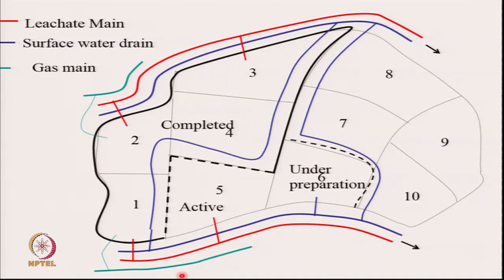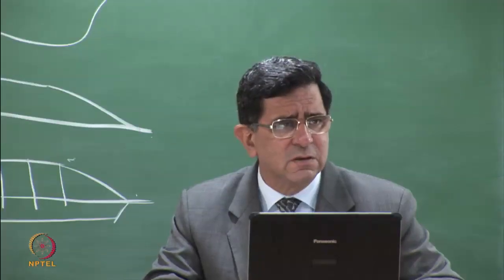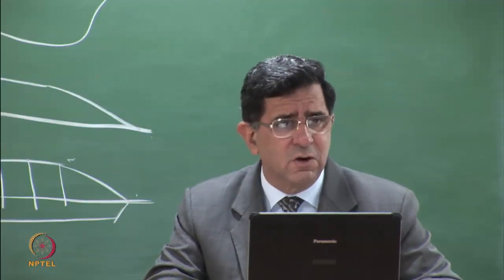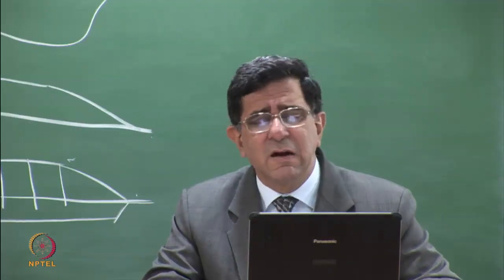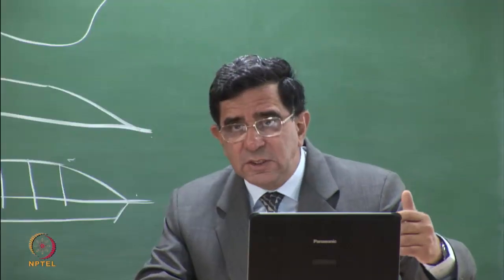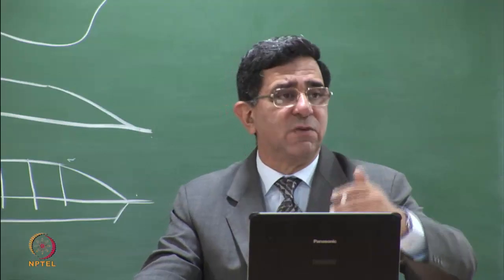Well, suppose the site is 800 meters by 1500 meters. So the perimeter will be 4.6 kilometers, and you'll have 4.6 kilometers of road. If you have the money to invest in 4.6 kilometers, fine. What he will say is, I'll make a cycle track so that my guard can go every day, but I'll only make the road as this progresses forward. Or he'll make a kacha road or something like that. So these things have to move forward step by step so that the expenditure is deferred step by step.